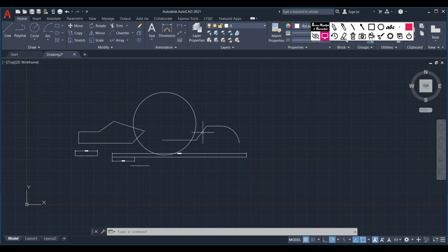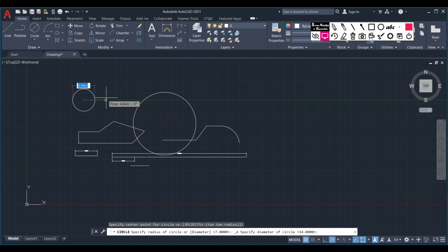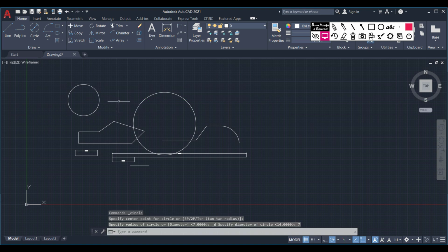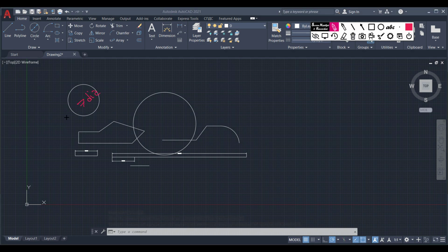Now if we go back here, suppose we need to draw a center diameter circle. If we specify 2 points, you can see this circle is specifying the total distance. Last time I specified the radius; this time I can specify the diameter. Suppose I press 7, this 7 means the diameter of the circle. You can see this is a 7 dia circle, and the dia symbol is like this one, and this is a 7 radius circle. That is the difference between the two circles.